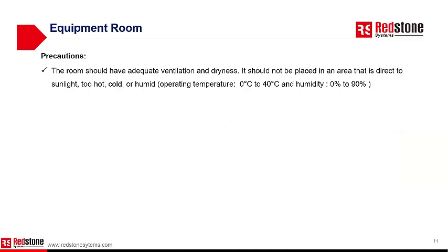The room should have adequate ventilation and dryness, and it should not be placed in an area that is exposed to direct sunlight, too hot, cold, or humid. The operating temperature should be within 0 to 40 degrees Celsius with a humidity of 0 to 90%.